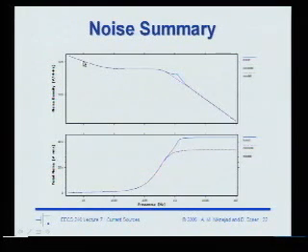If this blip had occurred over here in the flicker noise region, it would be totally negligible because delta x would be 0.1 hertz, or 1 hertz. So in fact, if you integrate the noise, boom, you see it. You see that the boosted amplifier, even though it just has one extra transistor, has higher noise.